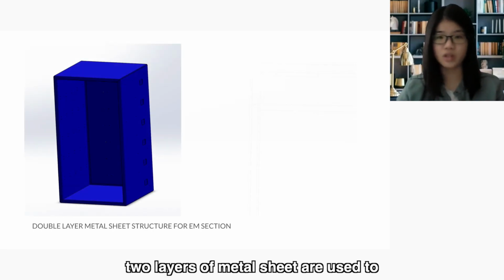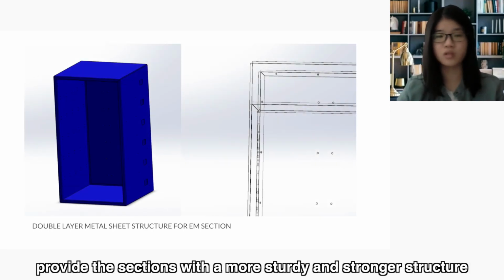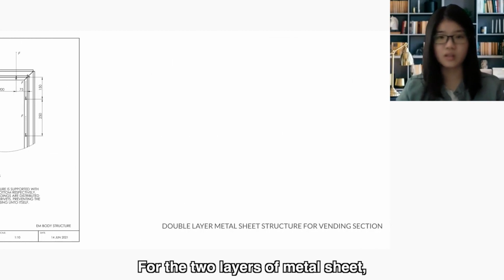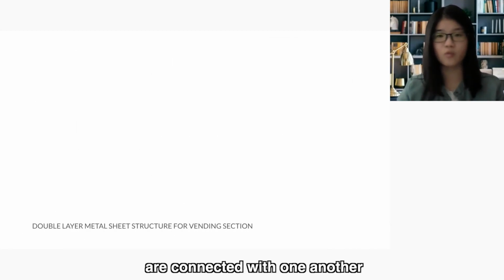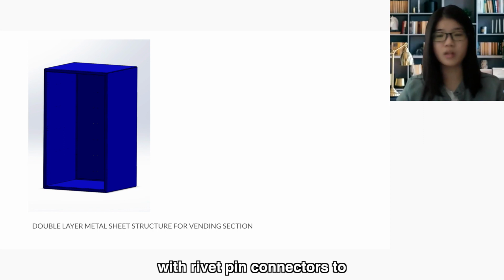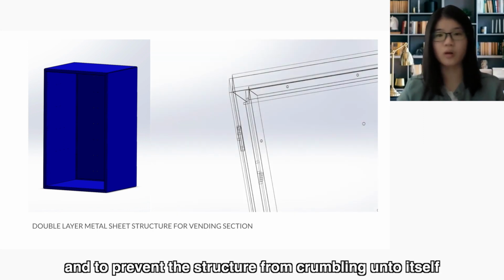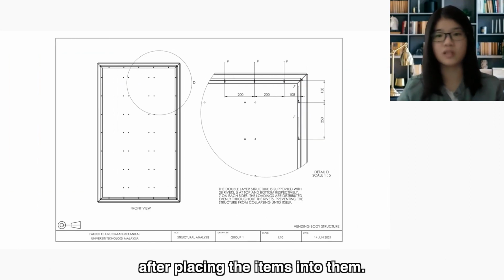Two layers of metal sheet are used to provide the section with a more sturdy and stronger structure as they store the items that need to be dispensed. For the two layers of metal sheet, the ends of the metal sheets are connected with one another using the rivet pin connectors to provide extra stability and to prevent the structure from crumbling into itself after placing the items into them.